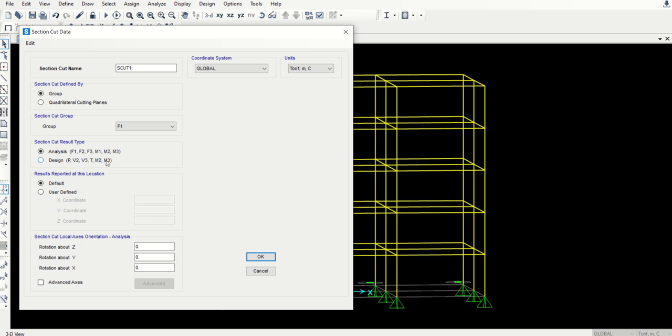When you have finite element models, for example, you can select an amount of nodes that represent a beam, and you can get the axial forces, the shear load, or torsion, or moments. You can integrate all the forces in the finite element model. In this case, we're considering only this option, and the others are default. Section cut orientation, all by default.